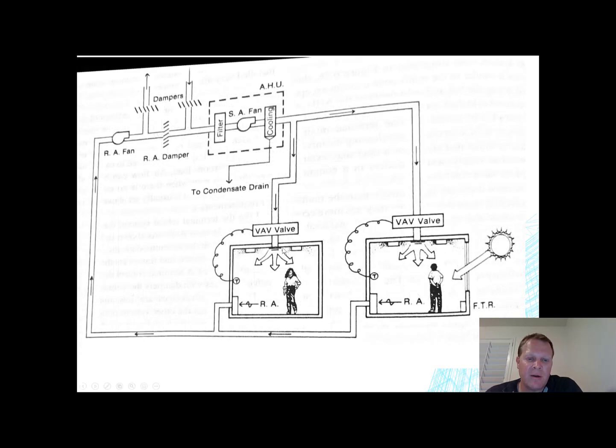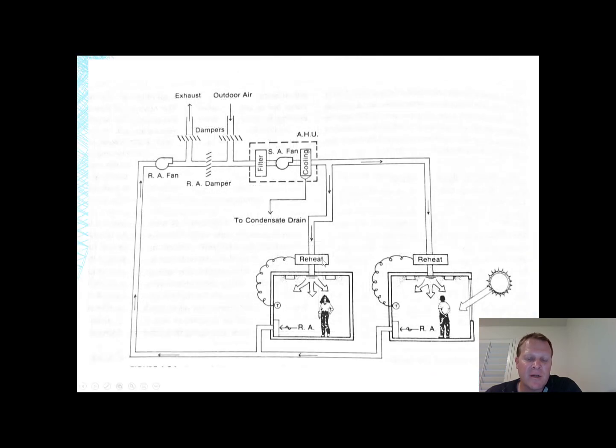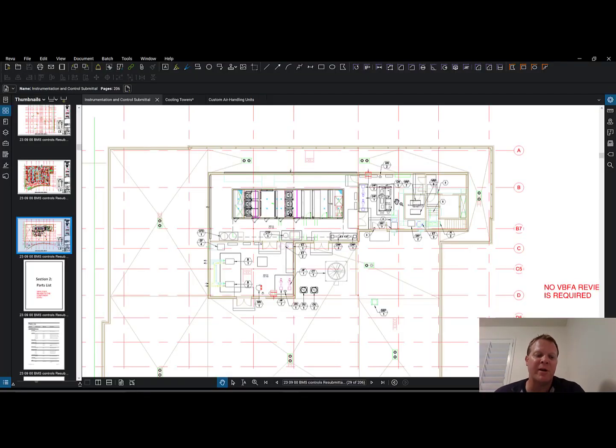And then we talked about how, well, let's control each of them with a VAV, variable air volume, right? Well, what does the VAV do? It's this box, the VAV box. It has a little damper on it that opens and closes, allowing more or less air to come in. Then we talked about how there was a reheat coil on that as well. A VAV with a reheat coil. And they could actually do more than just regulate how much air. They can actually heat the air back up. And that seemed crazy to everybody, right? So why would they do that? But that's how they do it.